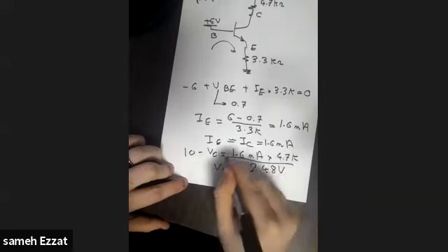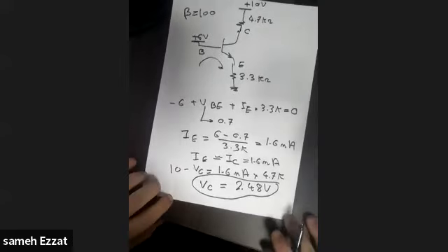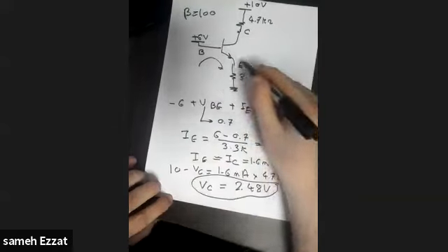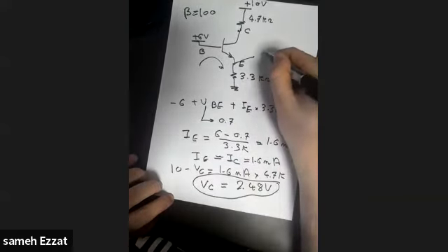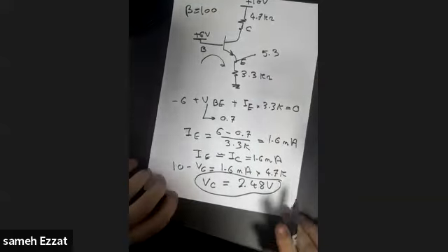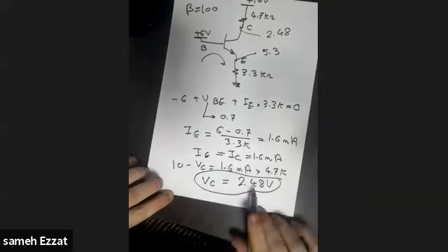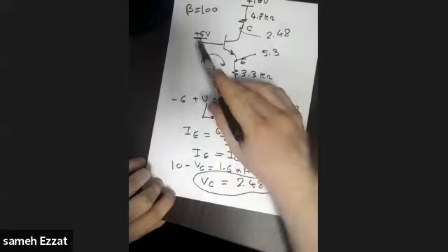So here we have to wait and see. Now, let's think. This voltage is 6 voltage. Here we have a drop of 0.7. So this voltage is basically equal to what? It's equal to 5.3 voltage to make this transistor on. We calculate this voltage and we find that it is equal to 2.48. That's right. Okay, 2.48. Yeah, that's right. So 2.48 and 6 voltage.